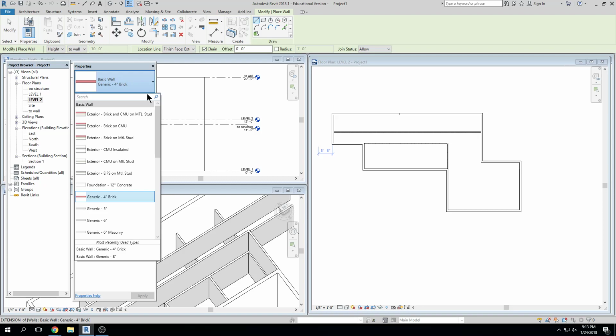So usually the workflow is you're going to have to show columns and architectural columns, but structural engineers have Revit Structural, or whatever it's called. The way it works is you give them your architectural model and they link it into their Revit Structural. They put in actual structural elements, and then those show up back in your model. So the two models and the two disciplines are working together to get those elements in there. It is magic, right? It works. The system works pretty well, actually.